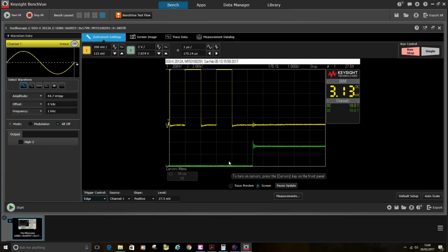I figure out this time here for this chip select turning off to the edge of this last clock, something like 15 nanoseconds, and hopefully you can see that we're on 1 microsecond of division, so that's 1,000 nanoseconds, and I'd call it another 500, so we've got 1,500 nanoseconds, and the limit is 15.